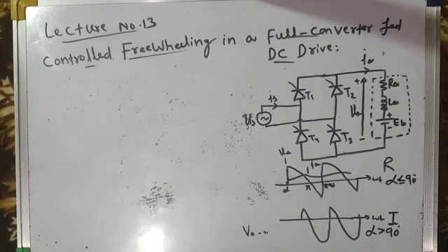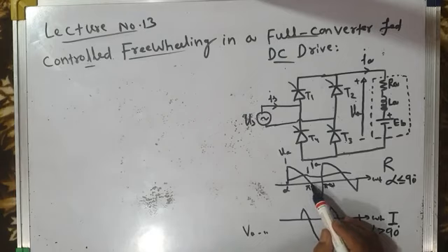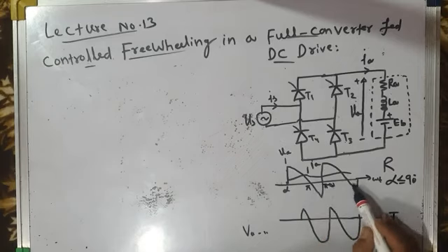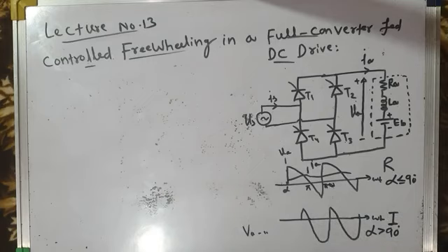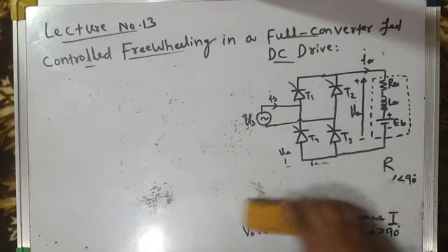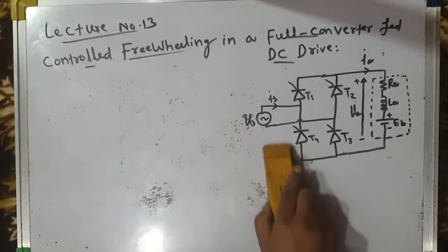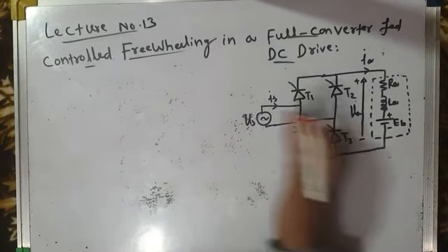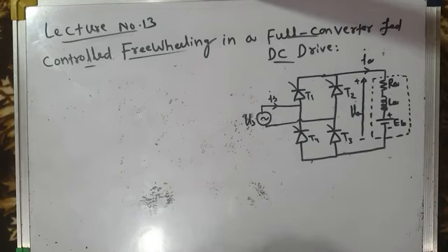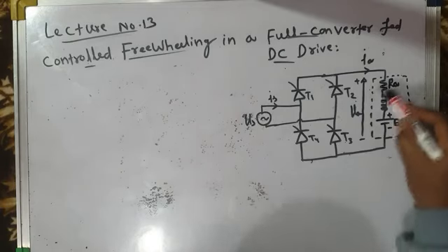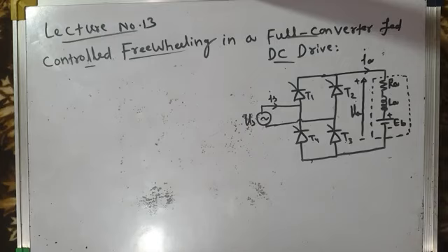If we are able to cancel these negative voltage segments in the rectification mode of operation, and in the inversion mode of operation if we are able to cancel these positive voltage segments, then we will be able to utilize this reactive power of the inductance and convert that into useful power, so that power does not flow back to the source, thus deteriorating the source power factor. That power is also utilized by the motor and converted into mechanical energy.